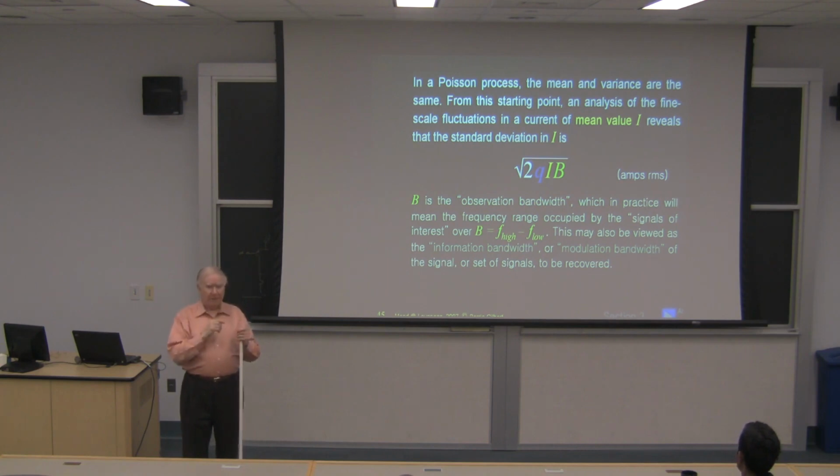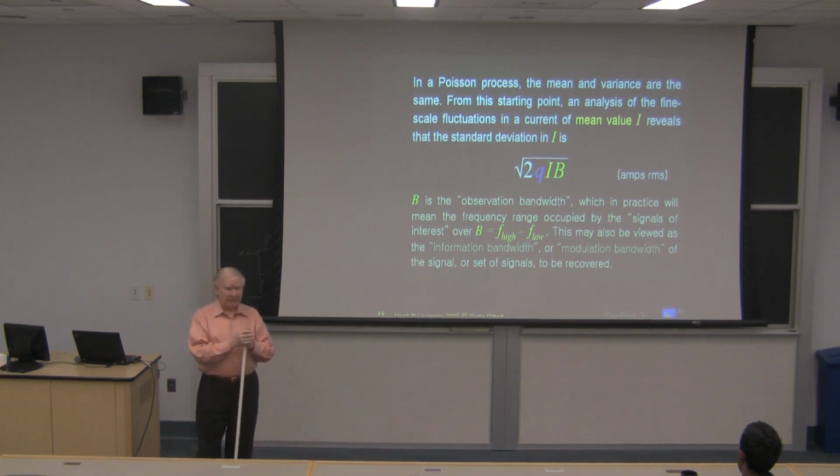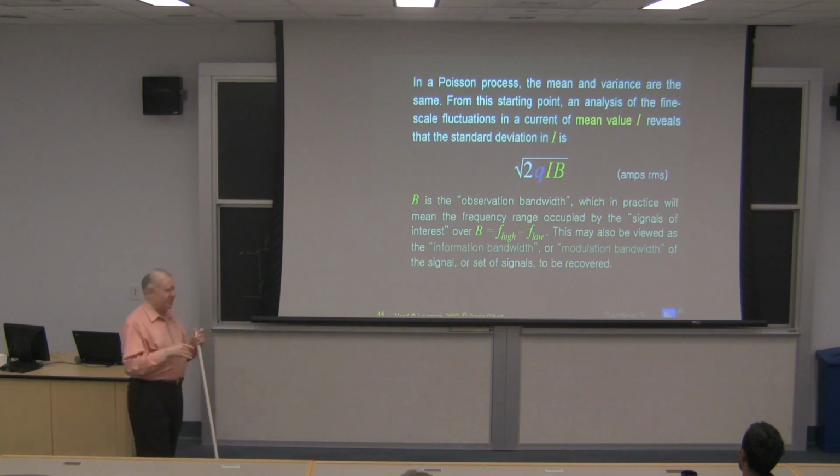If you measure 1/f over, say, a 1 second interval, that is, your measurement bandwidth for the 1/f determination is 1 hertz, 1 hertz by filter. And then you measure the 1/f over 1 day. It'll be imperceptibly larger. And of course, circuits switch off and on, so the idea of going back to DC is a bit silly.